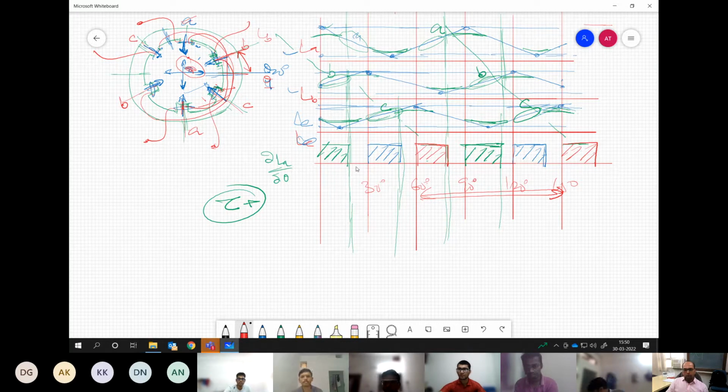So we are not continuously exciting any phase. We are giving current only at a particular position. When the coil is between 60 and say this 75 degree, then we are exciting phase A. That's all. Next we wait for the next sequence. Then after that, it is our phase B which is excited. That is 90 degree and 105 degree. Then again we go for phase C, 120 and 135. So these kind of repetitions would come for any given phase.